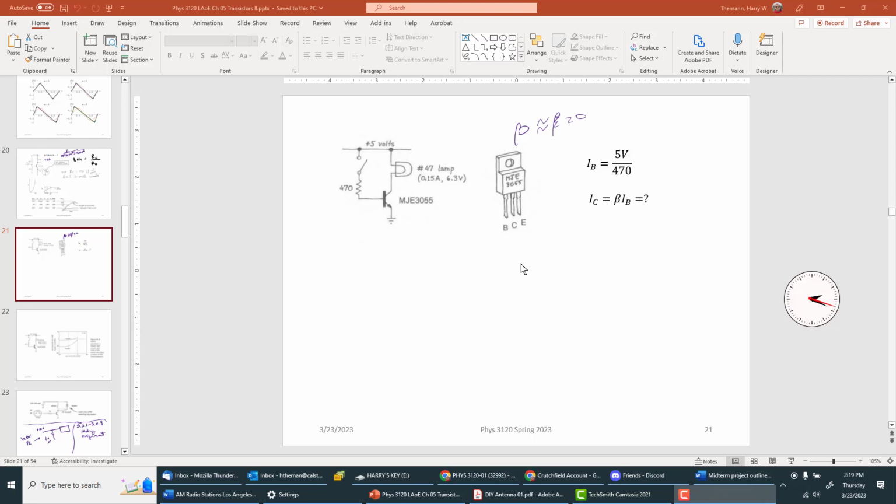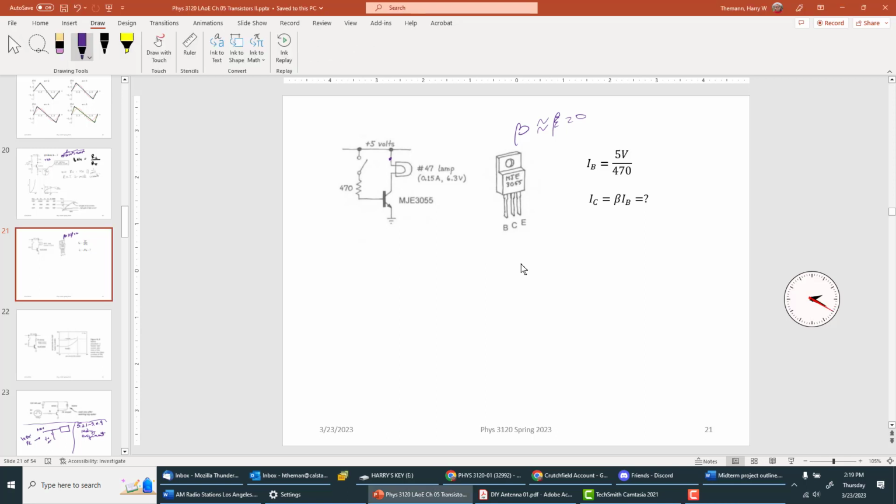And the thing is now, when you wire light bulbs together, I don't know if you realize this, but everything in your house is wired in parallel. So every time you turn on a light bulb or a motor or something, the amount of current going in through your meter on the outside of your home goes up. And it just has to be, number one, if a light bulb burns out, you don't want the whole house to not work anymore, right?